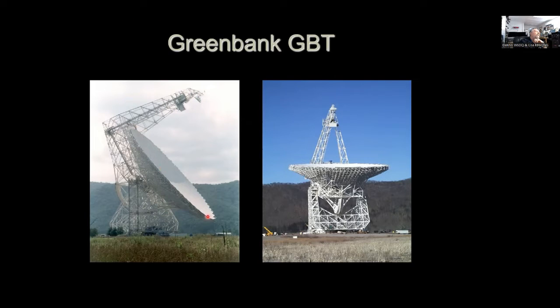So this is the main reflector. This is about 100 yards across, roughly 300 feet. There's a subreflector up here, and this is where the receivers and feed horns are, right there in this structure. This is considered an active surface. They use lasers to actually move the surface of the dish to correct it. That's how they can get this thing to operate up at 300 gigahertz, because they can actually manipulate the dish to make it optically correct.